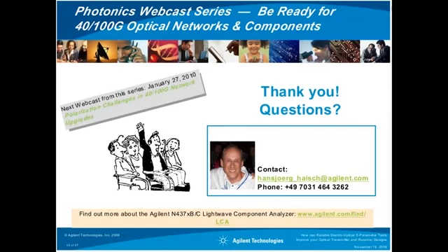But if you want to look beyond the noise effects, then it's also possible with the optical modulation analyzers, the 4391A. There are also ways to detect those mode hops by looking at the refined or high precision optical spectrum and a very high resolution spectrum feature, and then you can analyze the mode hops and the spectral changes on your device under test.